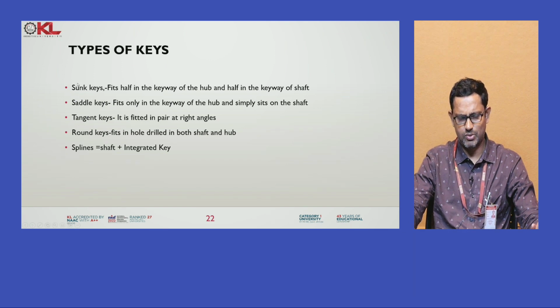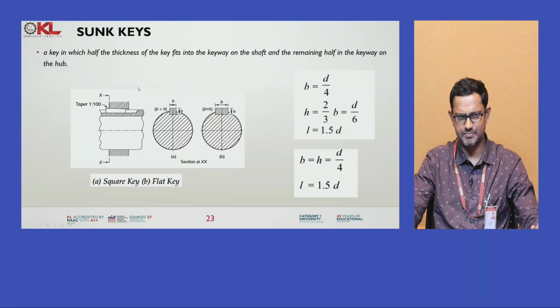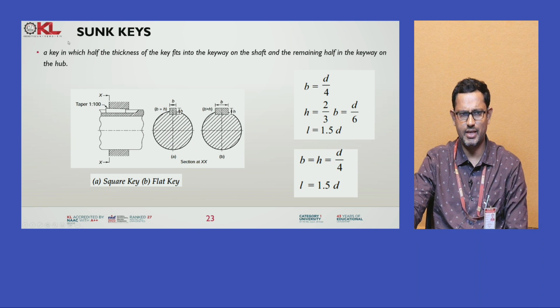Today's discussion we will see how to design sunk keys, because in this, half of the keyway will be in the hub and the other half in the shaft, and mostly these are the keys used for different applications. So let's see now how to design the sunk keys. As I already told you, in the sunk key, half the thickness of the key fits into the keyway on the shaft and the remaining half in the keyway of the hub.